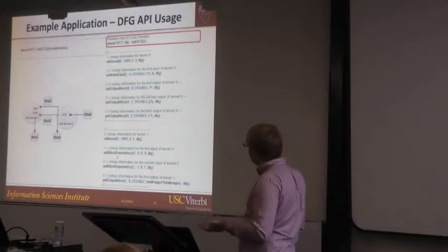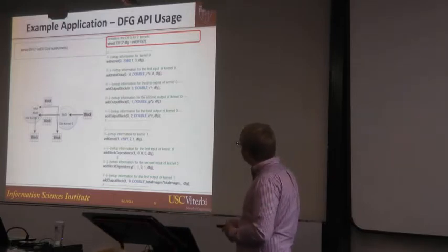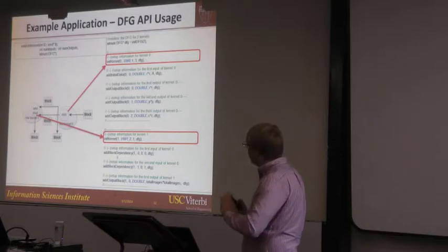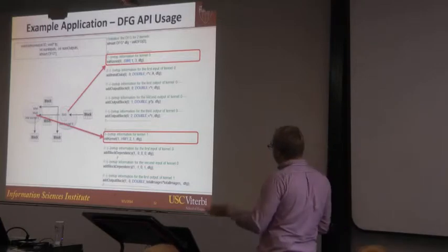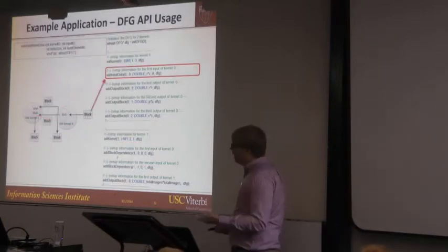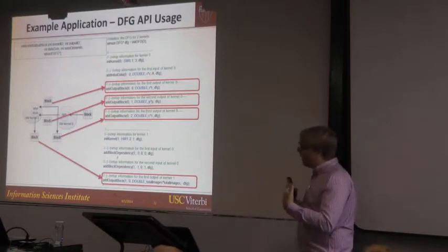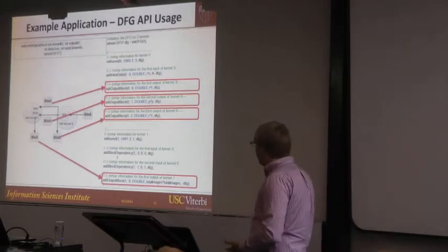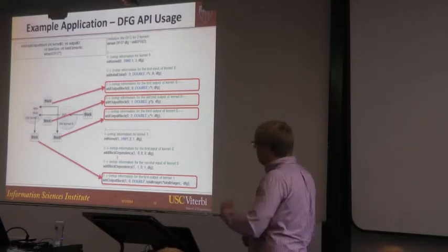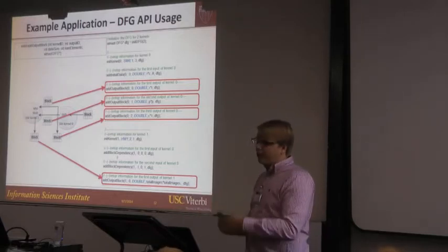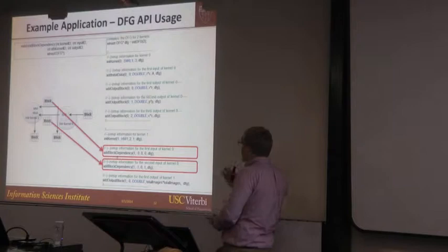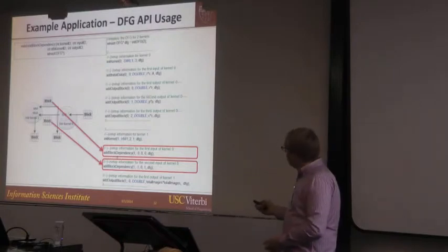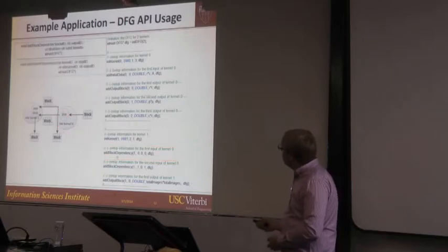So you specify the number of kernels in your application. In this simple one, we have 2. And you can specify for each kernel an indicator to what functionality should be executed when that kernel is run. You specify the number of inputs and outputs. You can specify initial data, and then the output from each kernel, whether it should be a block or a stream, how much space you need. And then these can be used during scheduling to determine how much memory to allocate. Should it be block RAM? Should it be DDR memory? But most importantly, you can also specify the dependencies between the kernels. So here's 2 block dependencies, but also we have output stream and stream dependencies as well.